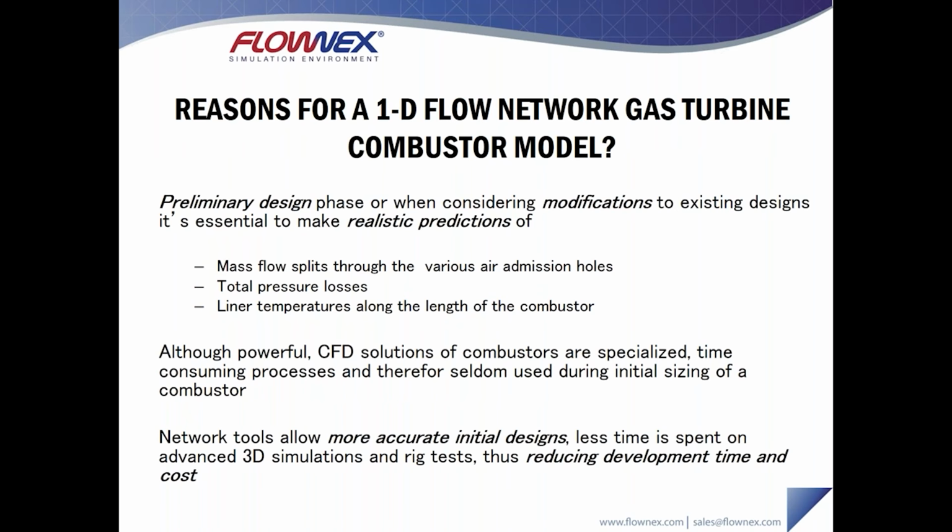the preliminary design phase, or when considering modifications to existing designs, it's essential to make realistic predictions of mass flow splits through various air admission holes in the combustor. It's critical to be able to predict and determine total pressure losses, and then also determine what liner temperatures are along the length of the combustor as well. So although this is possible to do with full 3D CFD, CFD solutions are specialized, time-consuming processes, and therefore seldom used during the initial sizing of a combustor. And that's where Flownex really fits in.